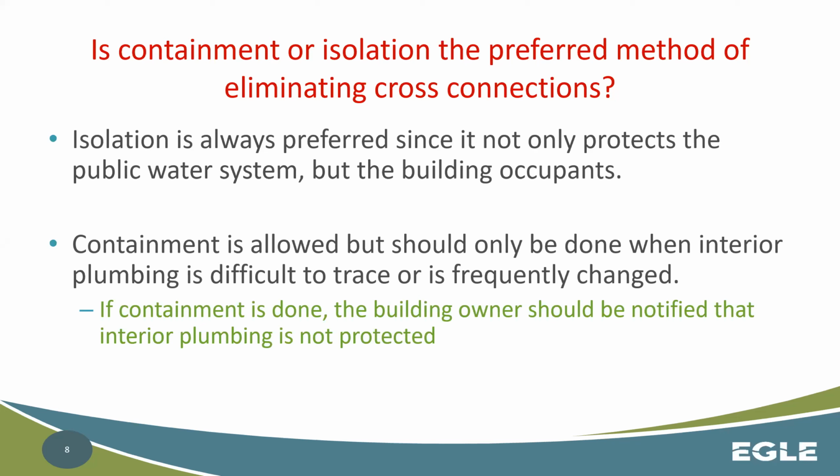Anyone who's an industrial or commercial customer should almost always have containment on their lines, always. I know most cities that I deal with, it is on there. They have at least a minimum of containment within their ordinance that is required, okay? If you don't have that in your ordinance, I highly recommend you put it in, and you should update that, okay?